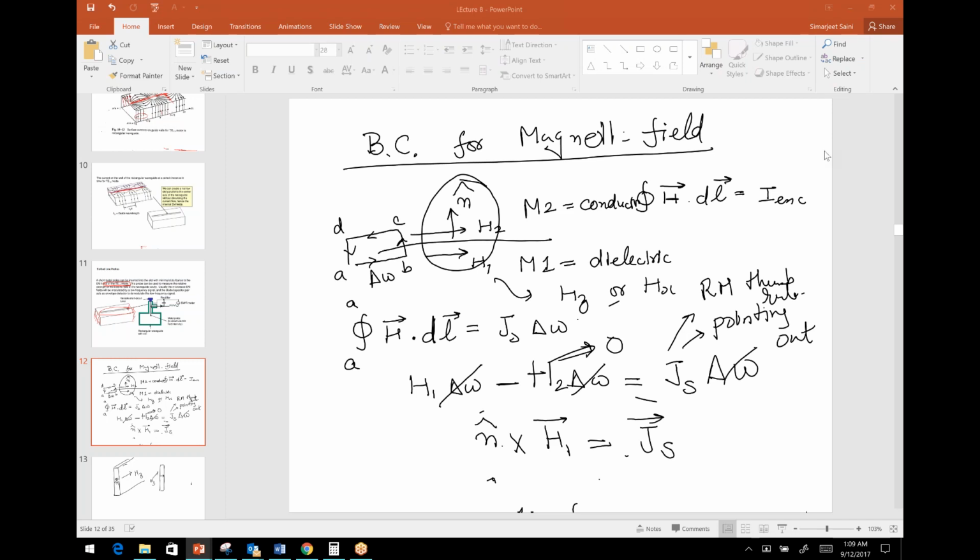When you go to further high frequencies, if you go to terahertz, which is a few hundred gigahertz, normally 500 gigahertz, which is again another interesting area of research these days, because a lot of materials have direct vibrational absorptions, and thus you can use that for sensing purposes. If you go to terahertz, then any metal becomes very lossy. So the metals don't work very well. So people have started using silicon, which is a semiconductor material.